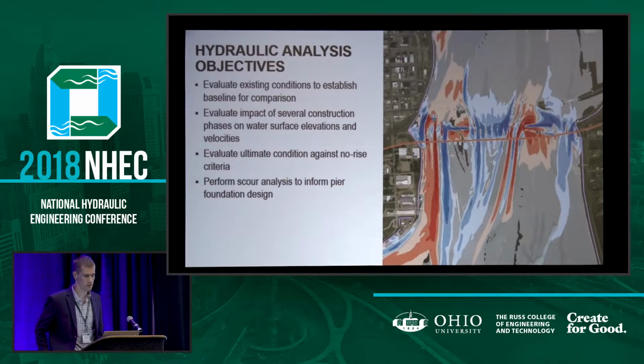So the objectives of our hydraulic analysis were primarily to support floodplain permitting and Section 408 authorization for the Corps. The Iowa DNR will actually review a 2D model for no rise, and the Corps wanted to see the 2D model for the Section 408.